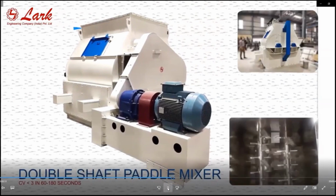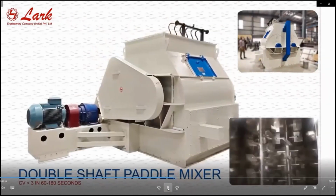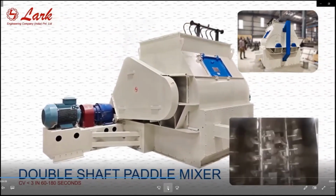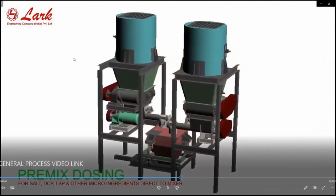This is a double shaft paddle mixer having CV less than 3 in 60 to 180 seconds. These are the premix dosing bins. For example, we have to dose the DCP, LSP, common salt, or other items directly to the mixer.